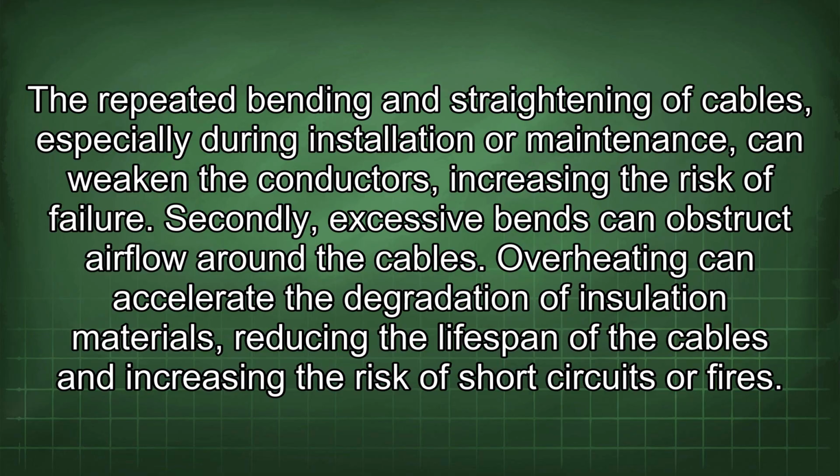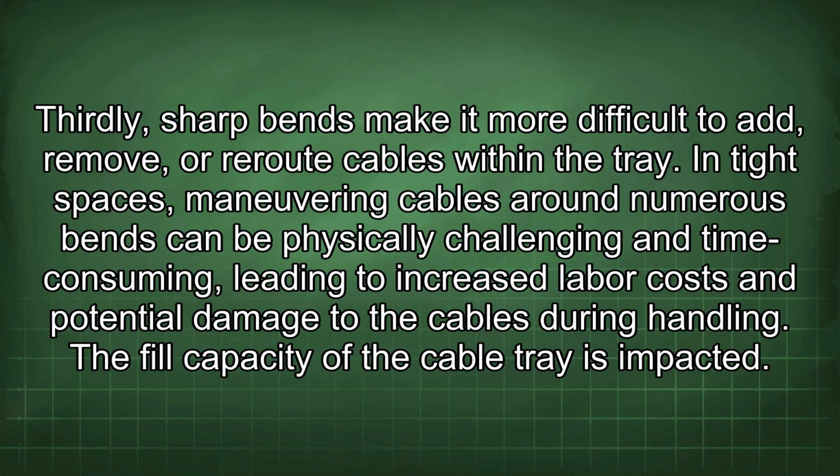Thirdly, sharp bends make it more difficult to add, remove, or reroute cables within the tray. In tight spaces, maneuvering cables around numerous bends can be physically challenging and time-consuming, leading to increased labor costs and potential damage to the cables during handling.